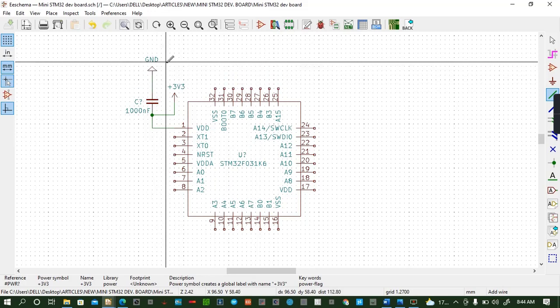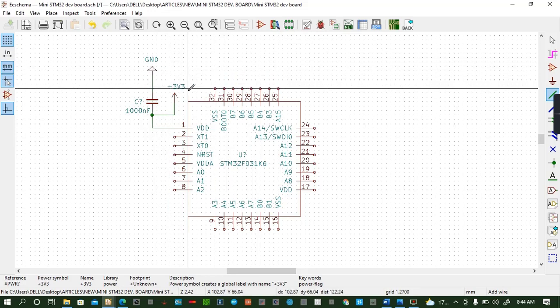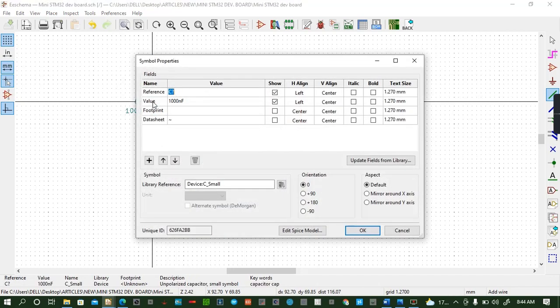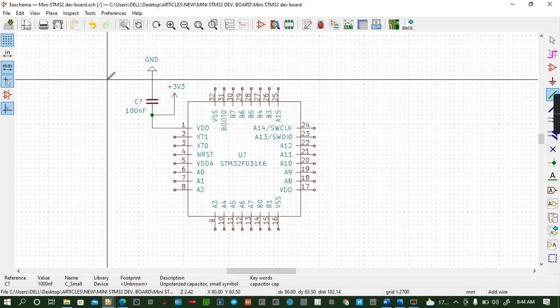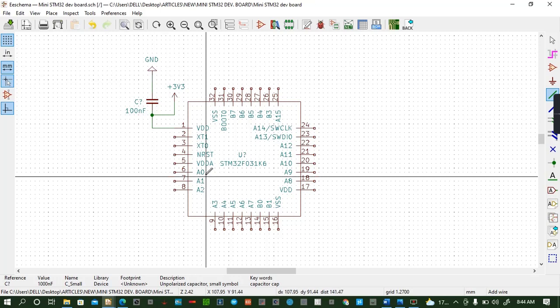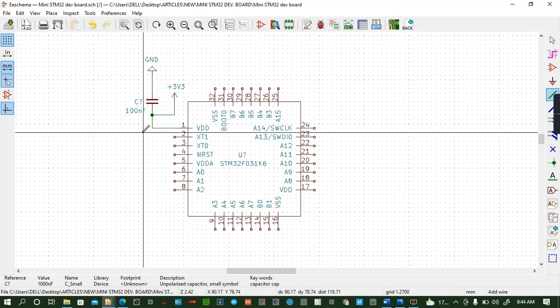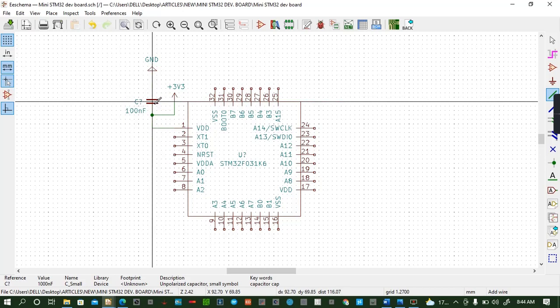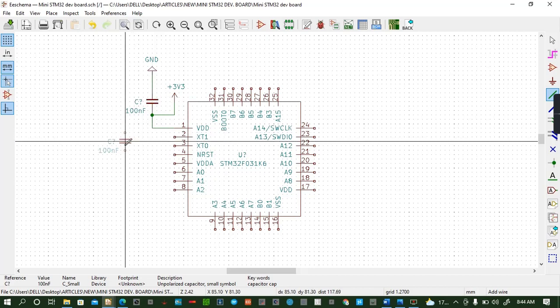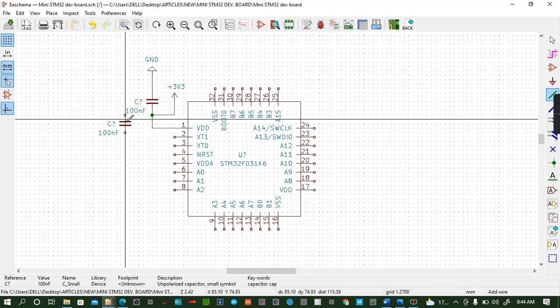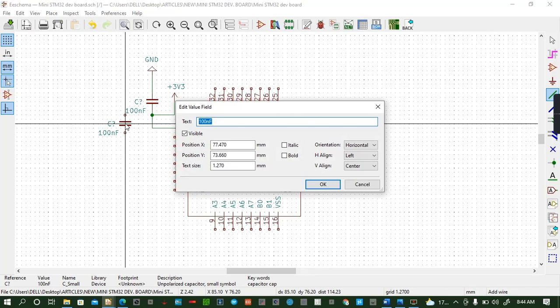After there, we need another capacitor. This one is 100 microfarad. I can edit it. This one I don't want it to be so big. Although the bigger the capacitor, these are coupling capacitors. So the bigger the capacitor, the less your device will be affected by noise. So we go to the next, so I can copy this capacitor, copy, like that. We need to edit it to 20 picofarads, 20 pF.